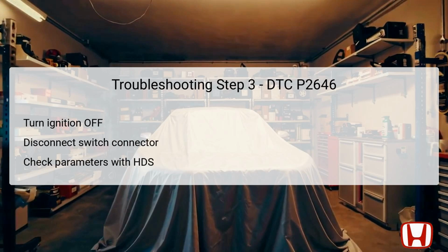In this step, the objective is to identify the possible failure area by examining the rocker arm oil pressure switch circuitry. Begin by turning the vehicle to off mode to ensure safety during the inspection. Disconnect the rocker arm oil pressure switch 2P connector to isolate the switch and prevent parasitic drain or misreading during diagnostic testing.